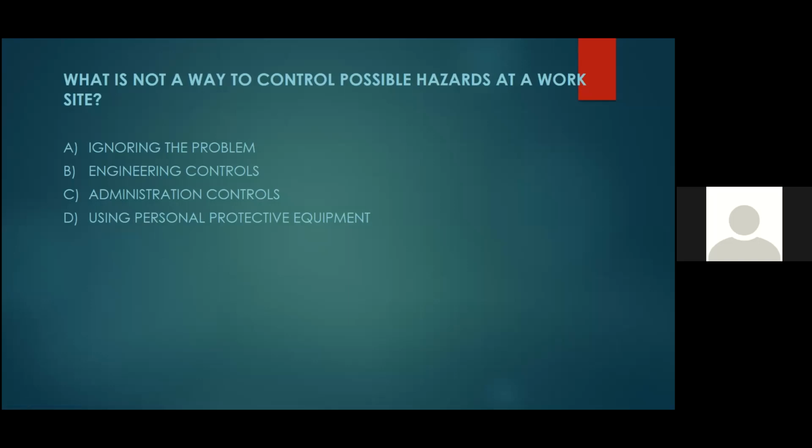One of the biggest things, and it's in order in this particular question, is engineer it out. If I have a confined space, is there a way that I can make that space safer? Or do I even have to go in that space? That's engineering it out, making sure we actually have to do this dangerous act, or whether there is another thing we can do that's safer. And that always comes first. That's the first thing you should always think about.